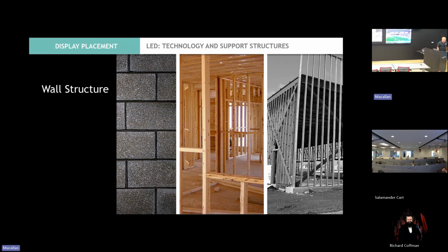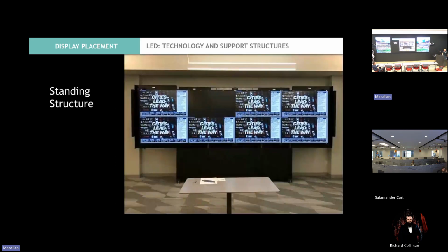It's probably 400 or 500 pounds. So it's spread over a certain area, but there are PE stamps that can tell us how much it's going to take. So at the time of design on the structure of the wall, they're going to know the weight of the whole metal work in the LED, and that needs to be passed on to the structural people for the buildings. So that's important to always keep a part of it.